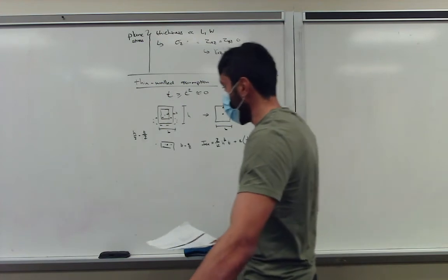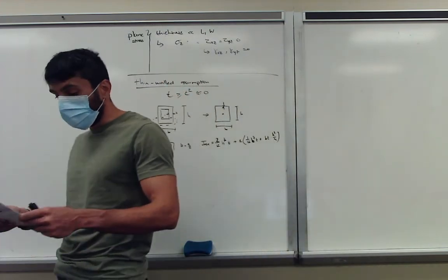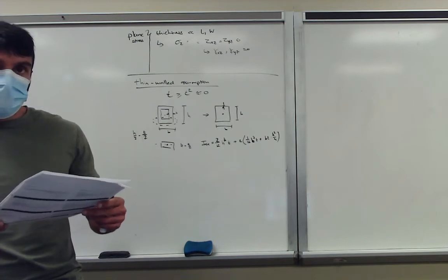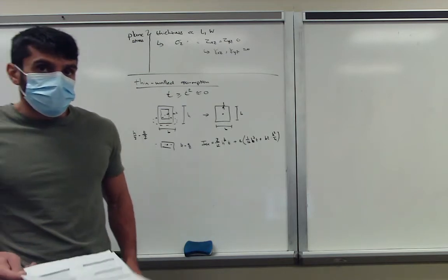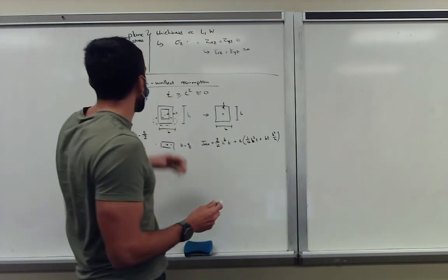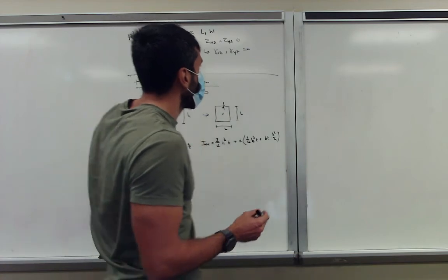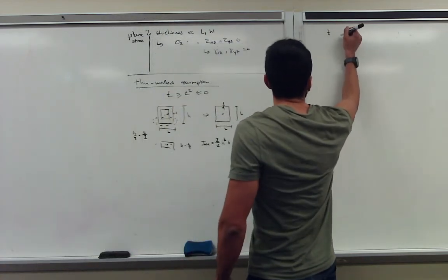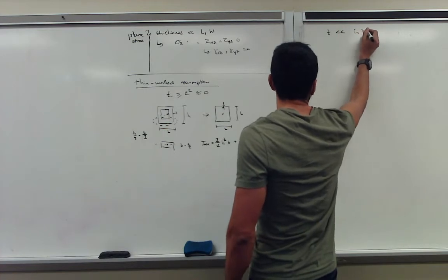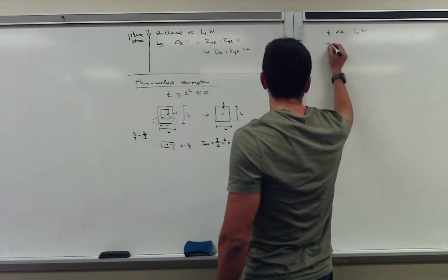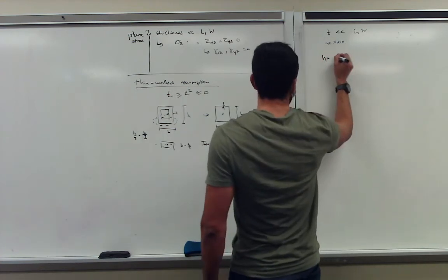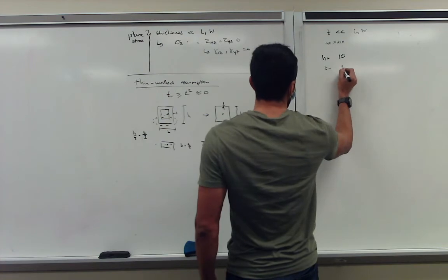And if you would plug in realistic values for the thick walled and thin walled, the differences are extremely small. Yes? So is there a thickness to width or thickness to height ratio we could look up to, like let's say we have a problem that says thickness is 2 millimeters? Yeah, that's a good question. So yes, this is valid under given conditions. Just like your plane stress, we didn't discuss that, but it's often valid if your thickness is significantly smaller than the width or length, and we are talking about a factor of like 10 or more. So if your height is say 10 units and your thickness is 1, you can use it.